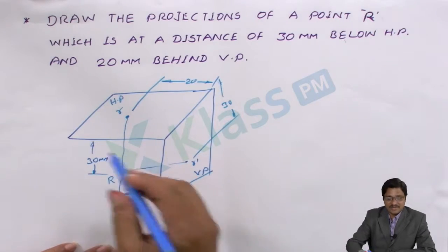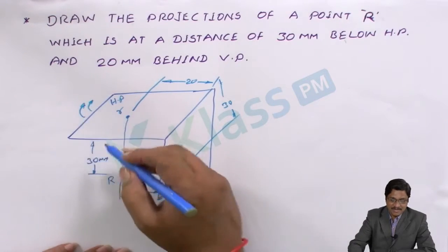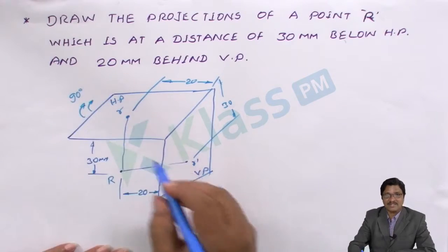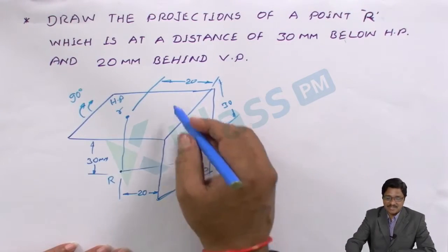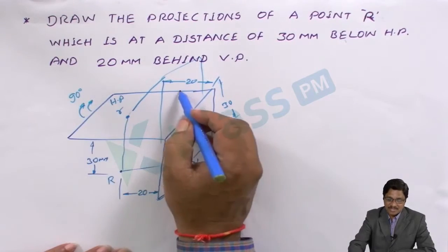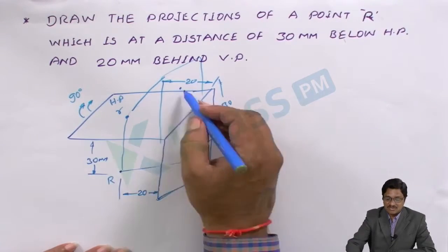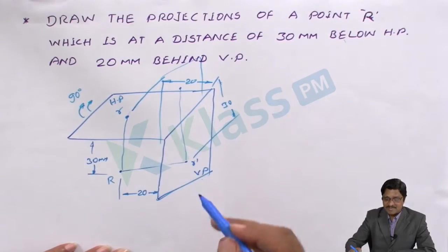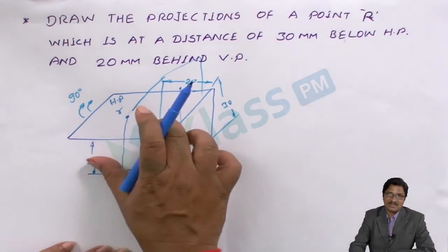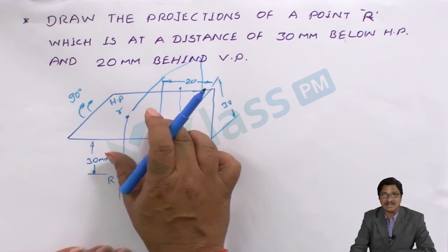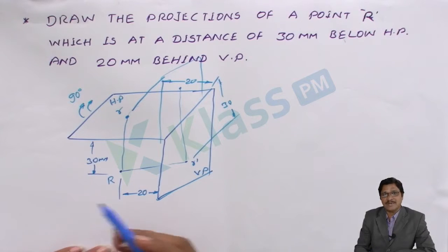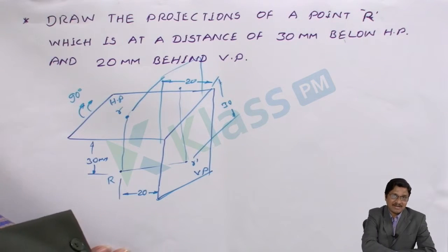After projecting, as per the normal standard practice, we have to rotate the horizontal plane 90 degrees in the clockwise direction. By that, this entire plane comes exactly above that one. When the projected views are also carried along, if you view them, both will appear on the same line. So this view is the solution you have to represent. This is the actual phenomenon you have to understand and imagine until you get the fundamental concepts. Otherwise, based on the fundamental concept, I can directly draw the solution.